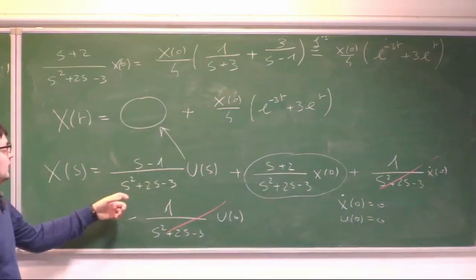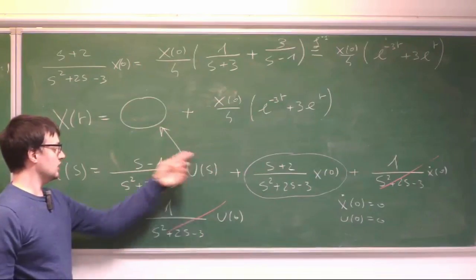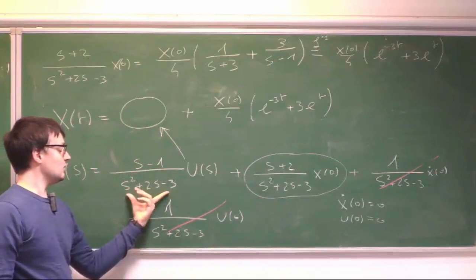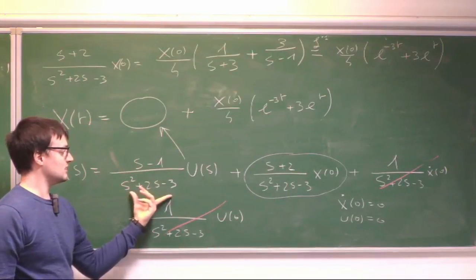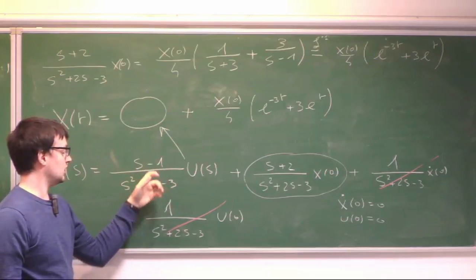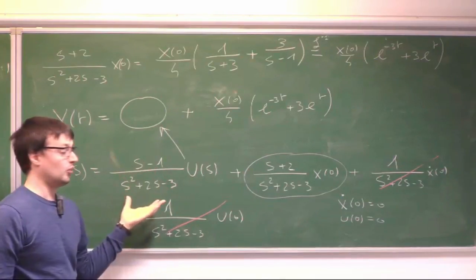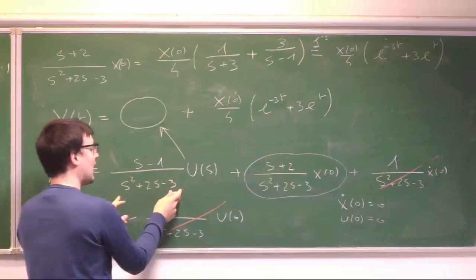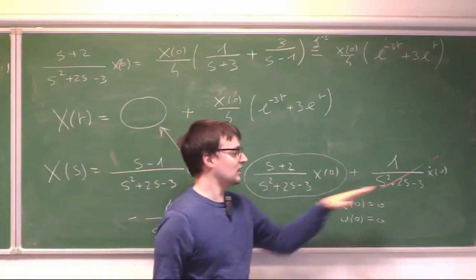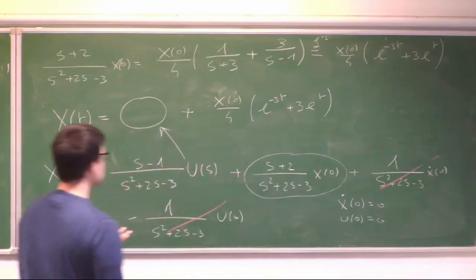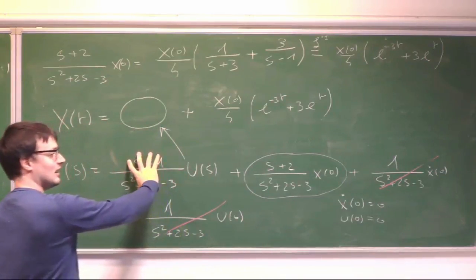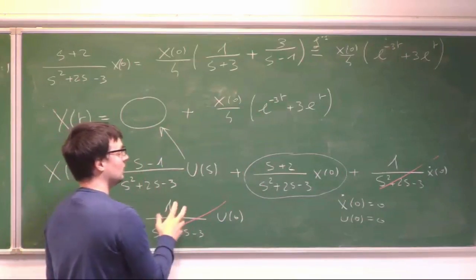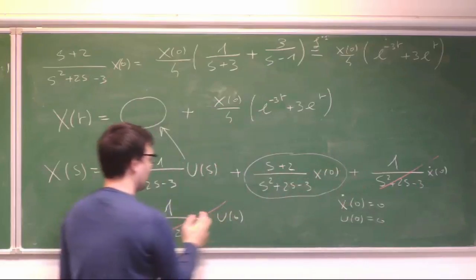So now, if here we make the cancellation, if we're studying only this term, because for some reason we are not considering the others, we will have the conclusion that this system is asymptotically stable if we make this cancellation, okay, and we are left only with a stable pole. However, we have to remember that the transfer function that we are studying is only one of many transfer functions that actually appear in our system. This means that even if here the unstable pole disappears because we make an illicit cancellation, that pole will still be there for the other transfer functions.